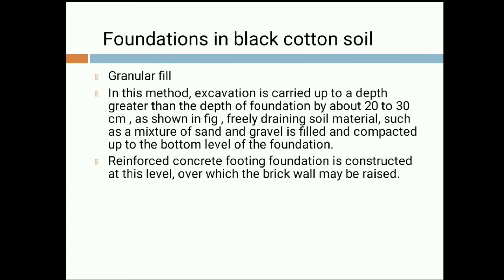Now let us see what kind of arrangement we can make so that we can form a foundation in case of black cotton soil. First one is granular filling. In this method, excavation is carried out to a depth greater than the depth of the foundation by about 20 to 30 centimeter as shown in the next slide. Means filling a granular fill 20 to 30 centimeter more than the original depth required for the footing.